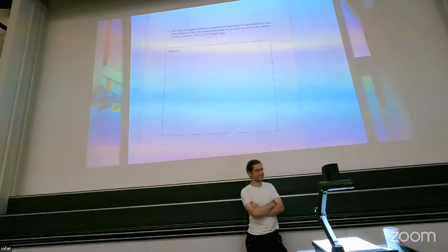The trick is that I apply the inputs so that, for the Moore machines, where the input doesn't change the output, the input will get sampled by this edge. Because I have a setup time, I want to give it as much time as possible, so I pull it back as much as I can, while staying away from the hold condition of the previous edge. Ideally I position it in between.